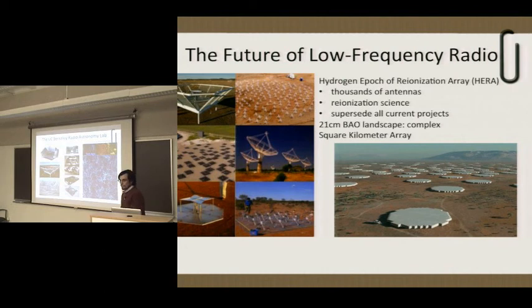So, looking at our 800 megahertz format maps, and it only gets worse at lower frequencies, we would conclude that, in fact, for our intensity mappings, the biggest single rate limiting step is polarization leakage. And you have to get to intrinsic. So if you only do lag filtering, you have to get that leakage down to less than 40 dB across the full primary beam. Is there any hope that these dipoles will have minus 40 dB? So these definitely do not have polarization leakage that low. We're more around 20 dB, just raw with these.